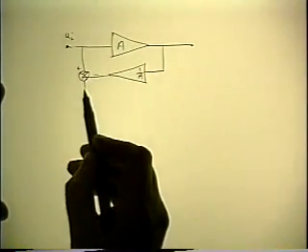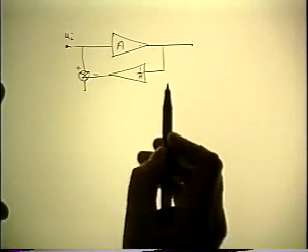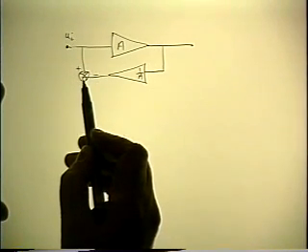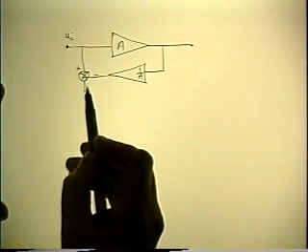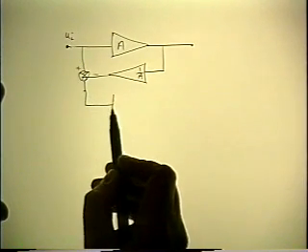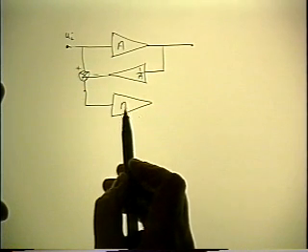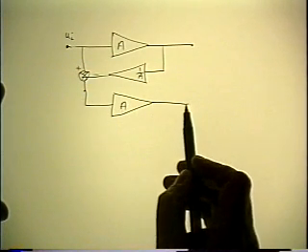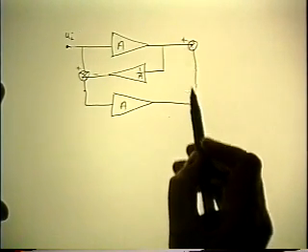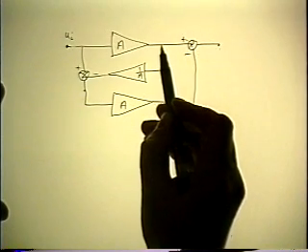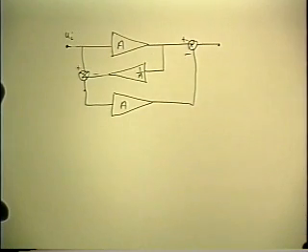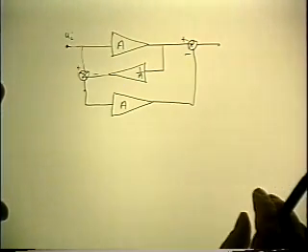So what we have at this point is we've attenuated the fundamental back to the same level it had to begin with, so it cancels out. And what we're left with is attenuated harmonics. Now we'll amplify the attenuated harmonics by the same factor again. So we now have harmonics of the same amplitude that we had to begin with, and we'll subtract those out, leaving the amplified fundamental and no harmonics, which is the objective.